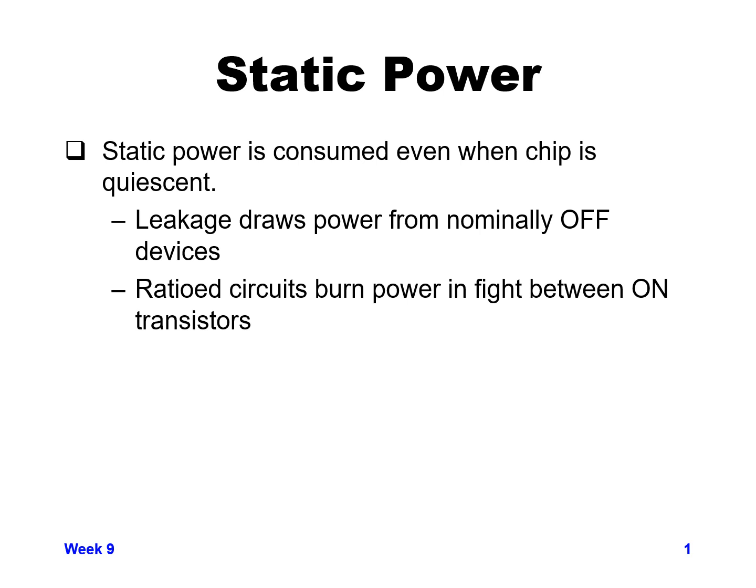In addition to this, if we have some sort of ratioed logic like the pseudo NMOS, which I don't like because that type of circuit will burn a lot more power than leakage power. You have a device that's turned on, and it's always on to some extent. It's not ever turned off. In pseudo NMOS, the device that's turned on is trying to pull up to 1, but the devices on the pull down stack are able to override and pull down near to 0.